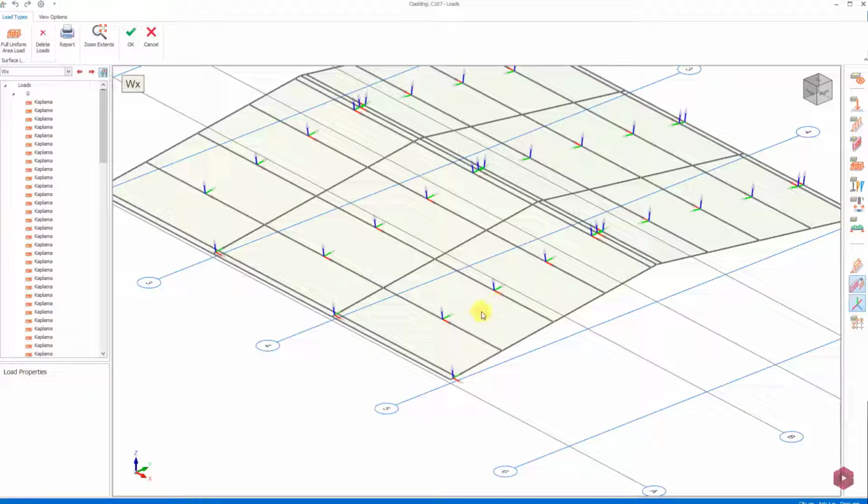After selecting the WX load case, let's choose the area load command, and we see that a label has been assigned as WX in the load properties section. In terms of direction, local 3 selection was made. Local 3 selection is determined automatically by ProtoStructure. Let's load 0.0962 as a magnitude value, then we can load all the panels by dragging method.